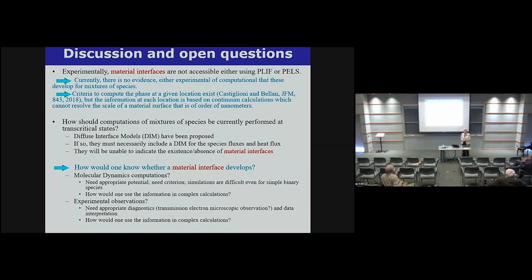Yes, that's what I said. They're increasing because with increasing Reynolds number, the characteristic time of the flow is shorter, right? But the diffusion time is the same. So by the time you get the flow to become what it is, diffusion can't catch up with it, okay? So that means that you're creating gradients, right?